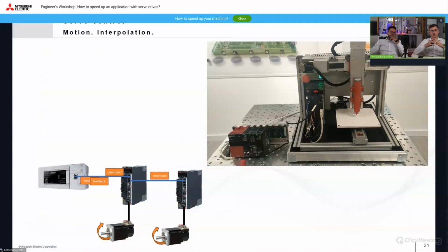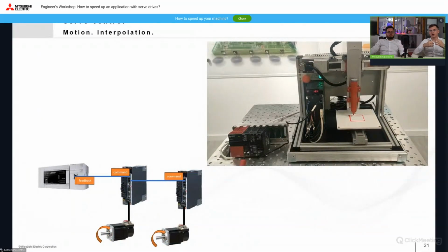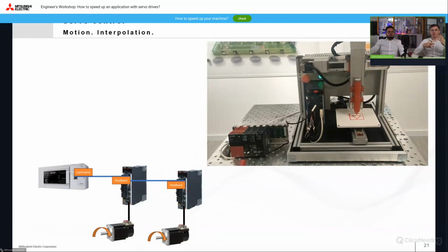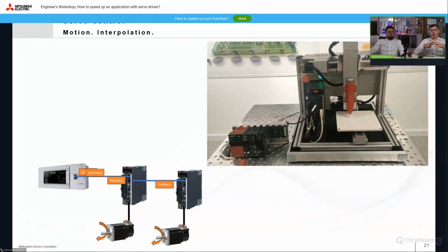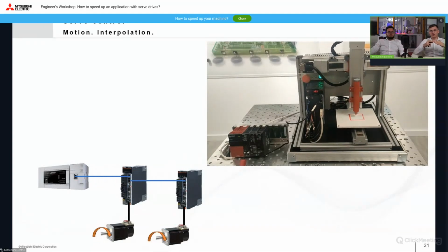And another variation of synchronization, often distinguished in motion controllers because of its ready-to-use parametrization functions, is interpolation. With it, we can combine the movements of two or more axes such that they make interpolated linear movements, as in the case of the square and triangle in the application shown, or circular in the case of the circle. Because of these uncertainties in the point-to-point control previously mentioned by Błażej, if we try to program an interpolation, for example circular, at best it would come out as an ellipse.